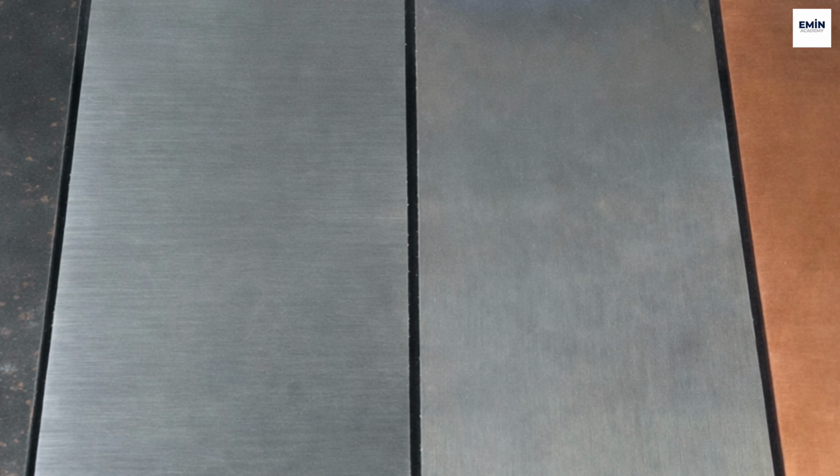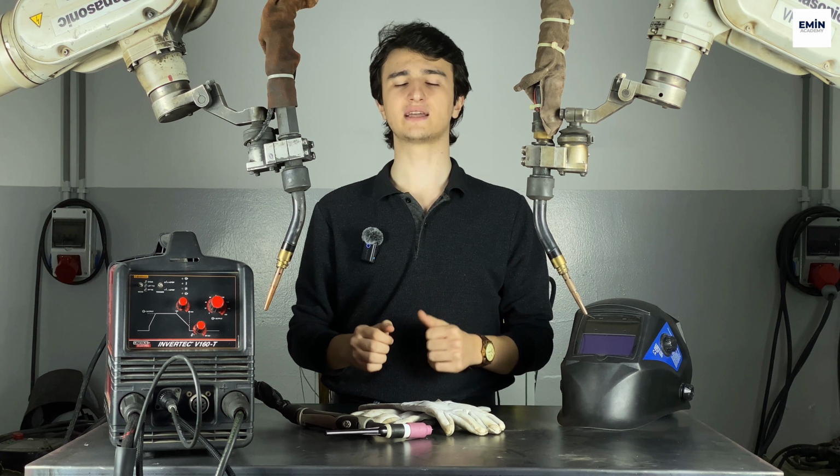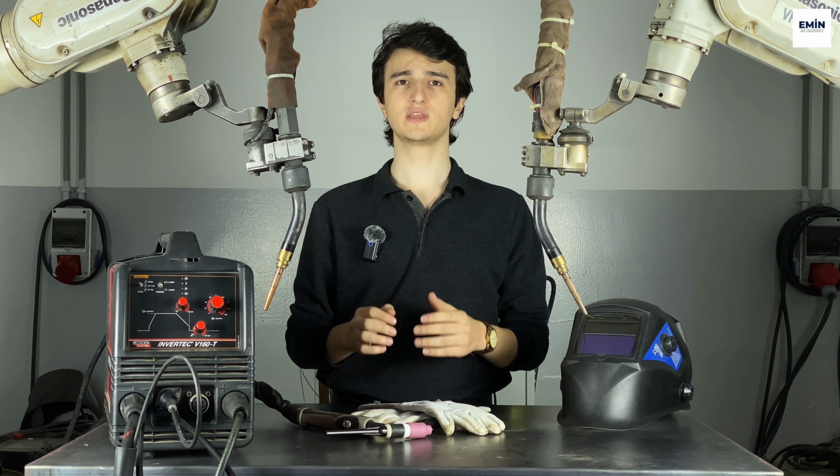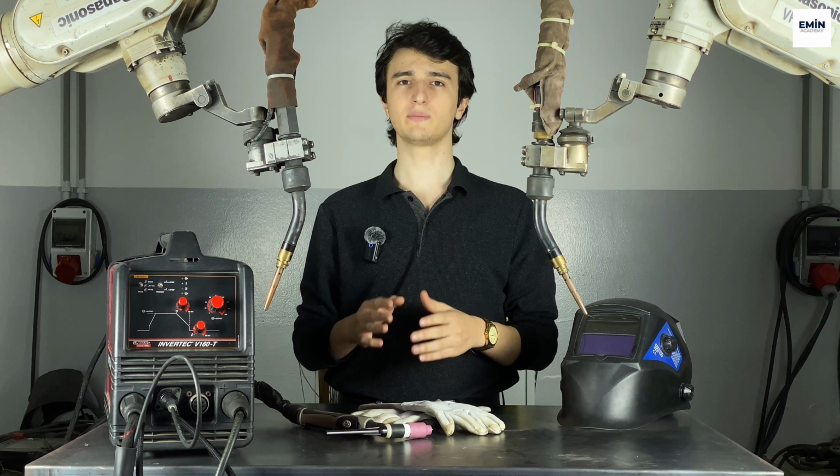That's why direct current is the ideal choice for carbon steel, stainless steel, titanium, copper, and their alloys. In summary, the advantages of DC electrode negative are a narrow, focused arc, high penetration, minimal wear on the tungsten tip, and a stable, quiet arc.